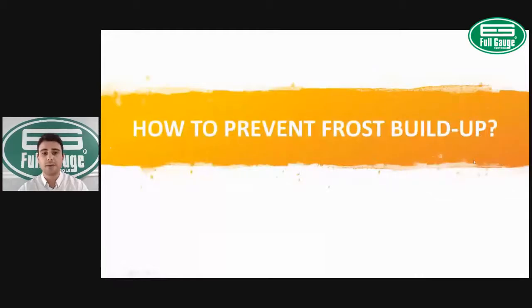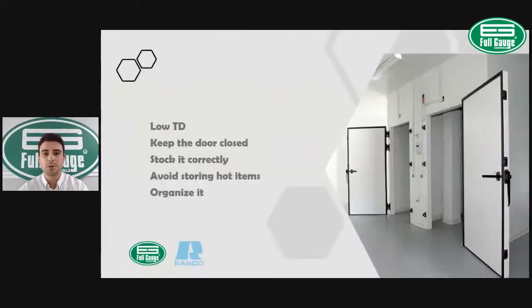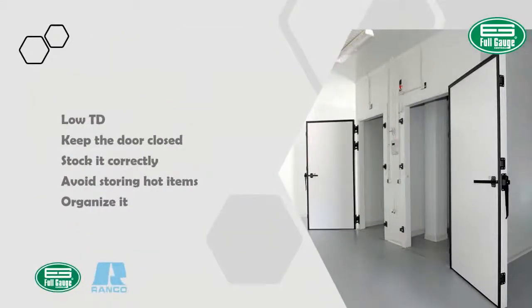Here we have a few tips on how to prevent frost buildup. First of all, frost is frozen water vapor. Ice forms when frost melts into water and the water freezes. The colder the evaporator, the more water vapor will freeze out of the air.